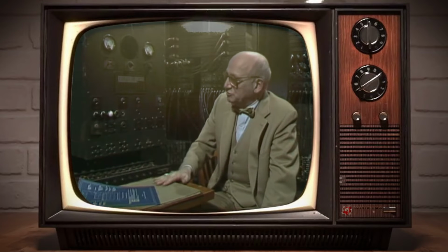Now, we could also turn the DC voltages off and have only the heaters on, which we frequently did during testing, because turning the heaters off and on due to thermal expansion in the tubes frequently blew a tube. In fact, if you turned the machine off and on once, you could almost count on it having one blown tube, where otherwise the machine would go for 1 or 2 days at a time without a blown tube.